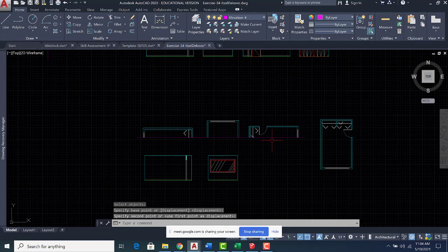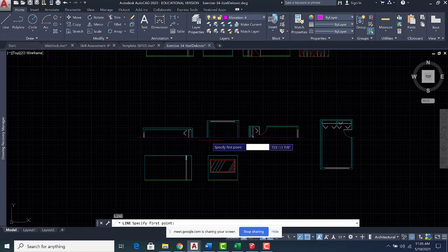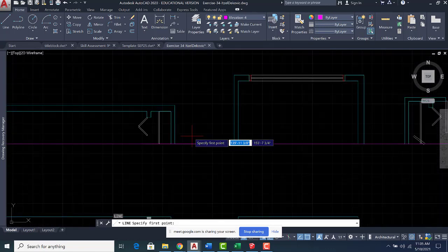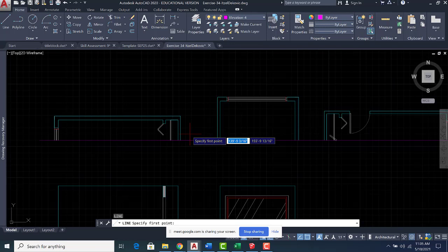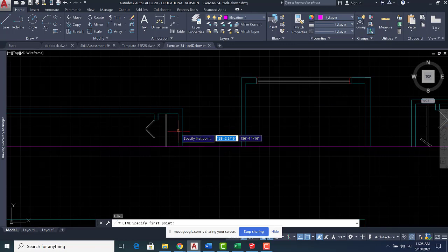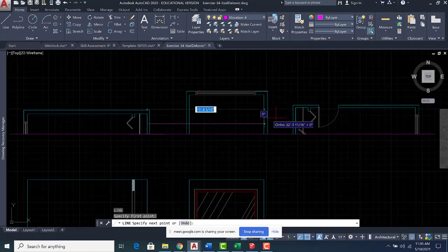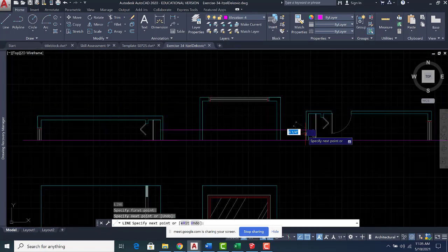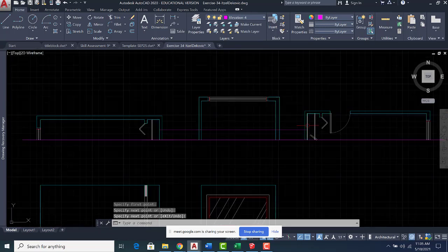So when I place that thing, the next step is, how can I mirror this? If I mirror this, I get exactly what I wanted. The only tricky part is you have to find the right base point. The base point for the center of your mirror, I always go with interior. Sometimes you might have a different situation, but the best place is the interior wall. See, interior wall to interior wall, perpendicular to this one. So now the distance of this interior wall to that one is the same.